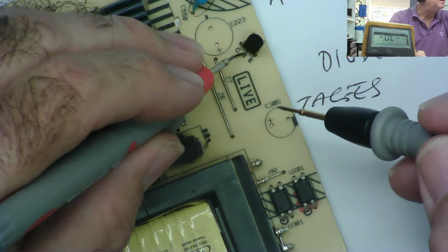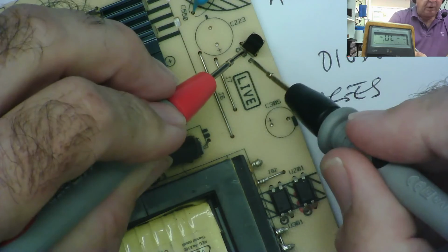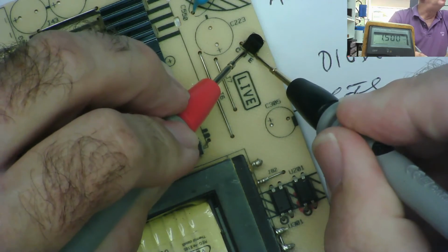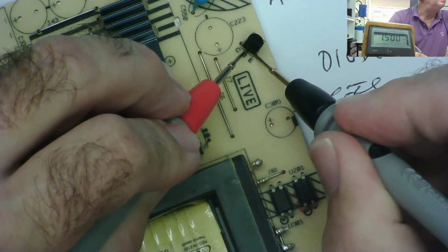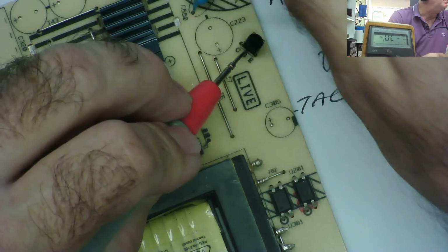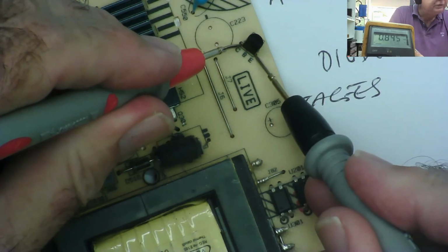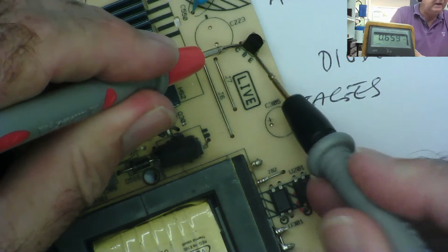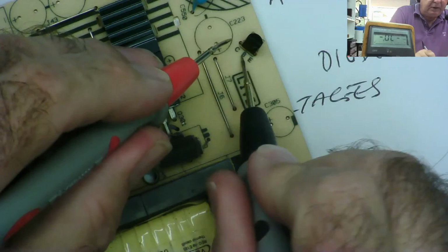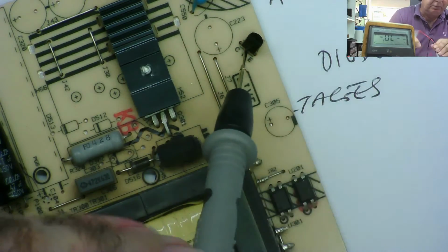So let's see if we can test it, see if it's NPN or PNP, or if actually we think it's good. So we know where the base is, it's marked. So let's put the positive on the base, negative on the emitter. Well, it's reading something, but it's not reading the diode junction, yeah? That looks like a capacitor charged up, so there's nothing there. So across the collector emitter, is there a short? No, I can see a diode junction, but not a short. So negative on the base. That's the diode junction. So it looks like it's a PNP.